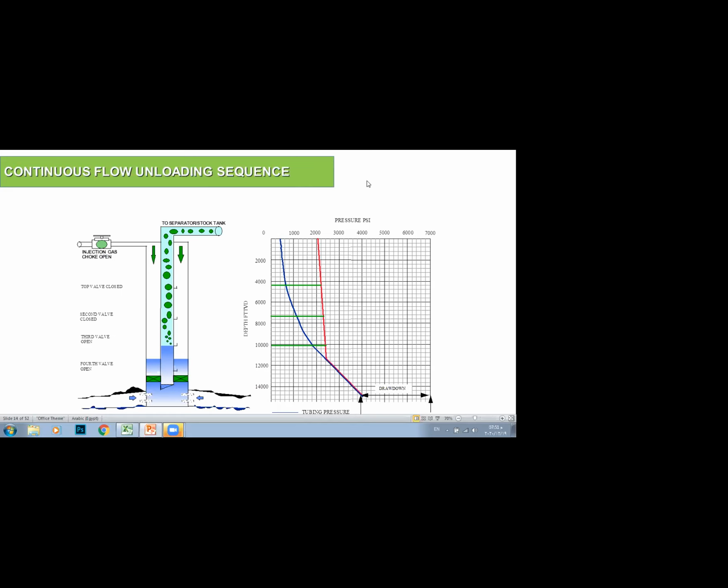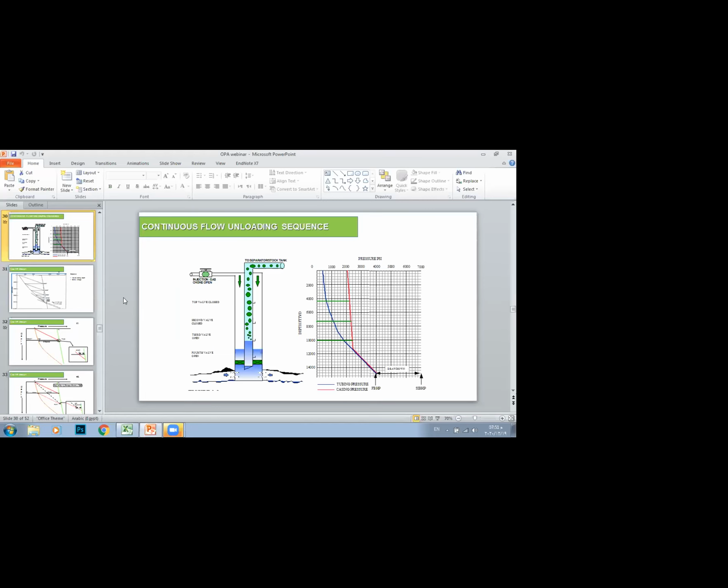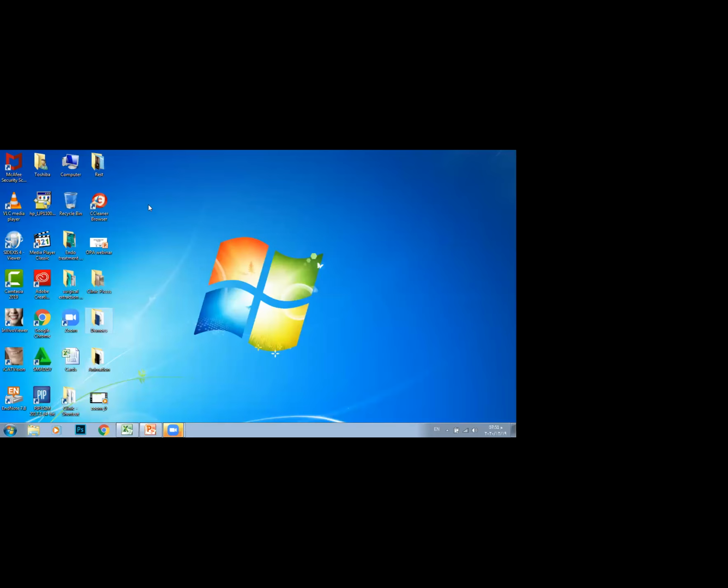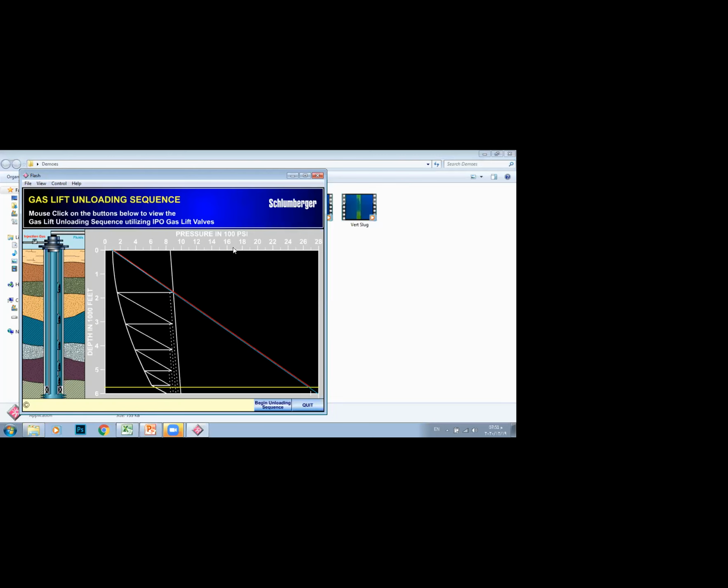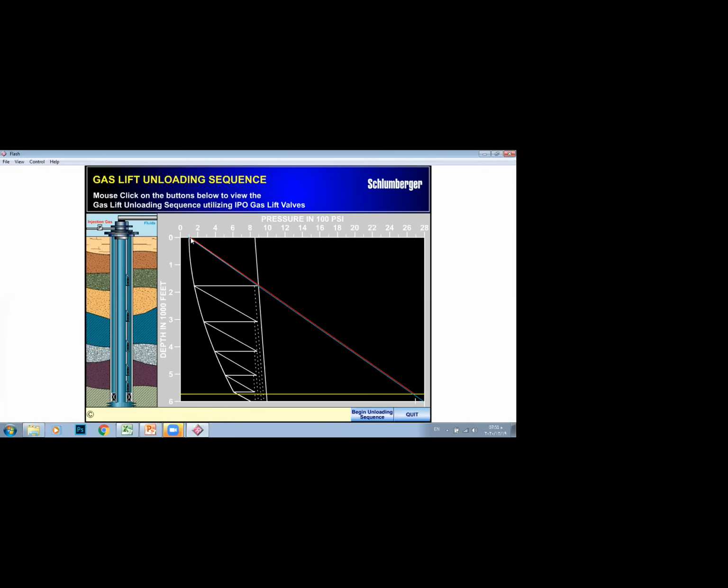I can show you quickly a demo showing again what's actually happening. Normally I have this chart, these lines. The well is closed. I have completion fluid in the well until the reservoir pressure. The injection gas is the red line. The blue line is the pressure inside the wellbore. Bear in mind, I want to reach this curve. I want to produce my fluid like this, and I want this to be my point of injection. So we will understand now what's going on.